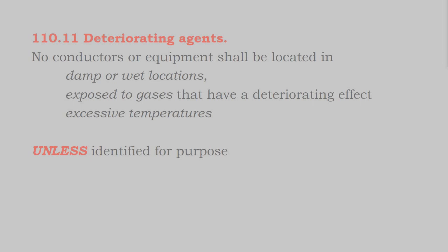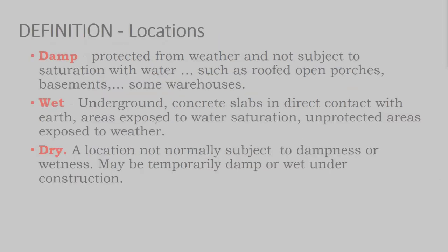And so what's complicated about on-site renewable design is that if you're a general contractor, general electrician, you just may not connect all the dots on saying, well, what's the difference between a wet location and a dry location? You might get to the store and realize, well, this cable is not listed for outdoor use. So we have to learn how to match all that stuff up.